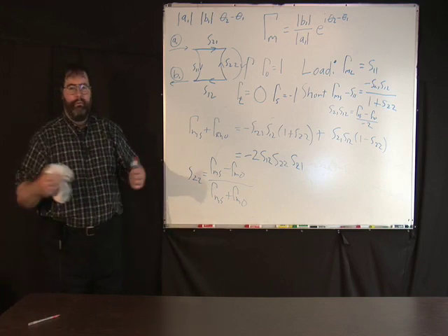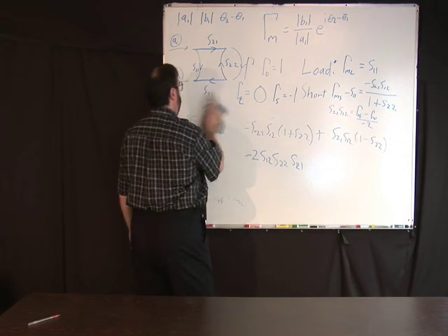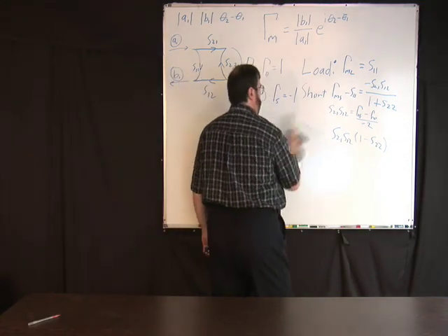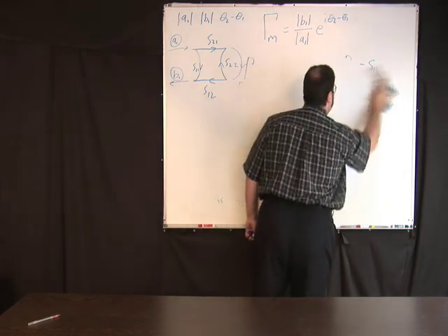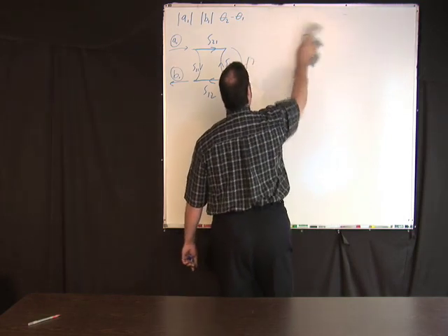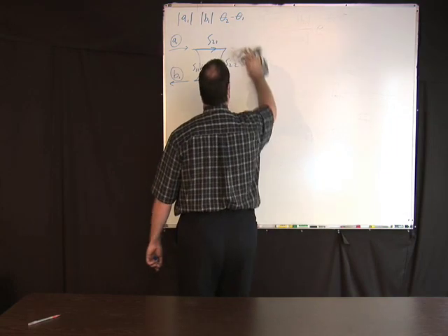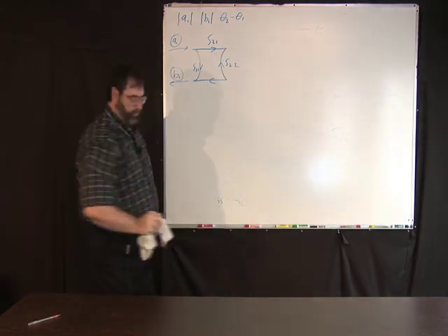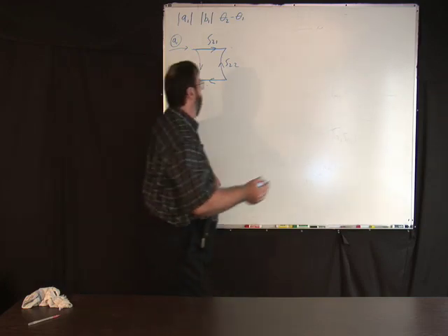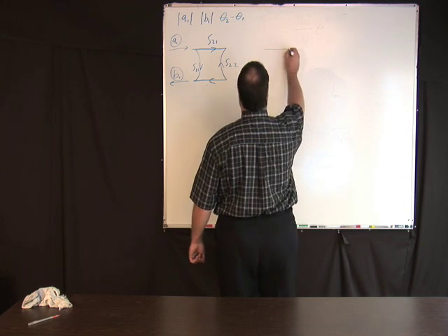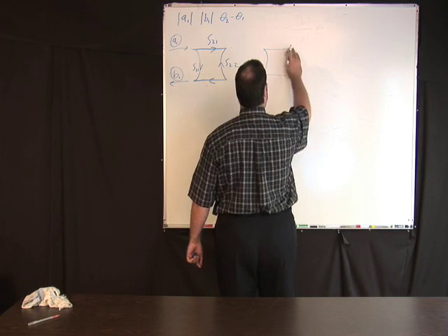Well, we have a little time, so maybe we'll go on to 2-port. Similarly, you can measure, this is a 1-port reflectometer or a 1-port network analyzer. But what you can do now to make a 2-port network analyzer is you just put another coupler with its own error model as a second port.